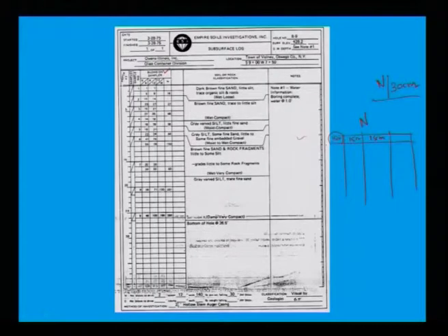So, first 15 centimeter penetration is say N value 2, second 15 centimeter is say 4, third 15 centimeter say 6. So, generally N uncorrected should be 6 plus 4, it is 10. So, instead of providing N corrected to all, sometimes they provide 3 N values, every 15 centimeter N values. That is also another way. It will be an easier job for sometimes the design engineer, sometimes the field engineer.